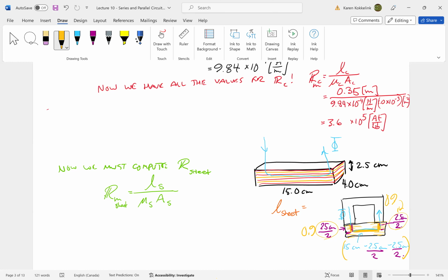When you're doing a laminated section, you even have to take just the laminate of going across, even though you could be going across inside entirely sheet steel, we still take 0.9. So our mean path length of this sheet, the length and the width is derated by the laminations.